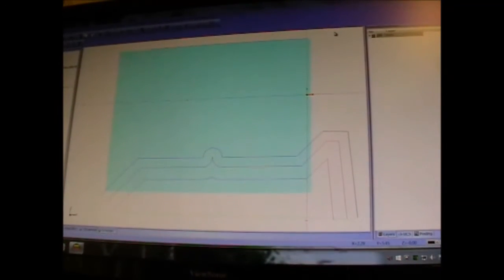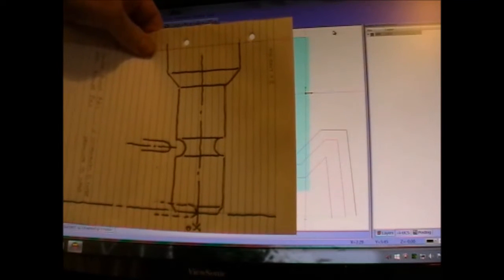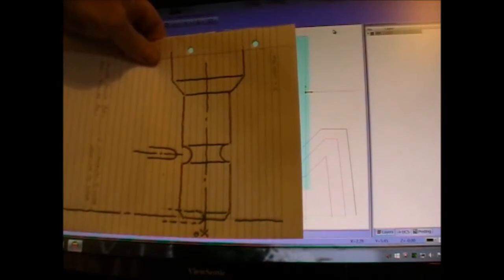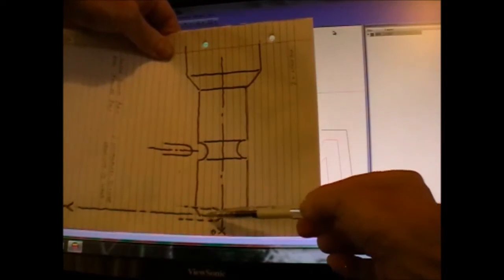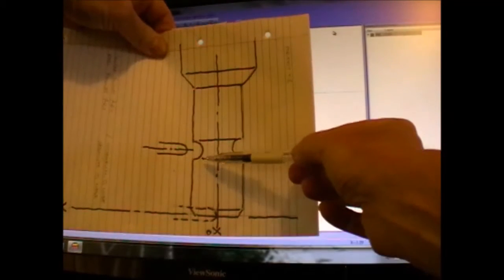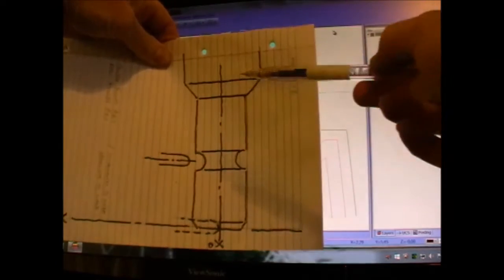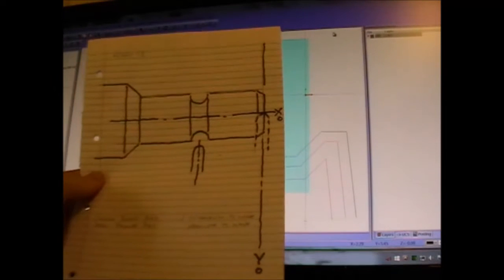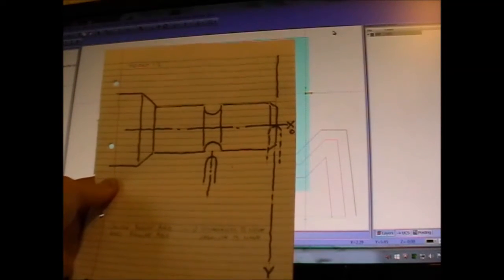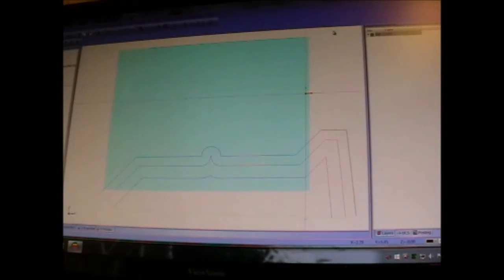Okay, first of all, let's go through the CAD CAM. To start with, we want to end up with a turning setup in the mill spindle like this. We're going to turn it vertical shape here with the tool on this side. We're going to turn a chamfer, a diameter, generate a circular groove, and then a chamfer out or an angle out. But we're going to format it with our milling CAM software in this direction like this.